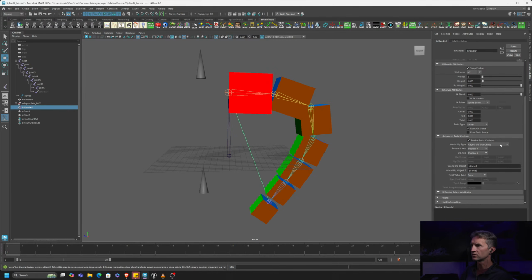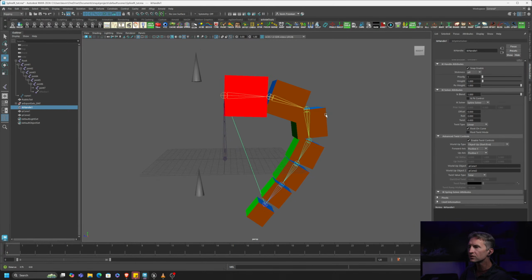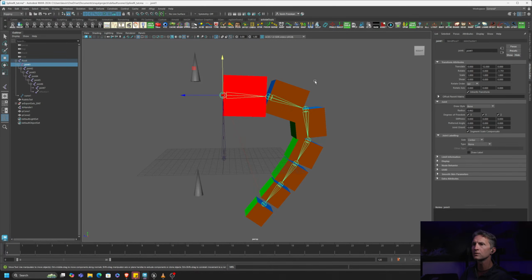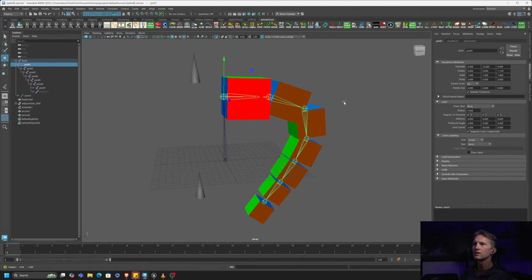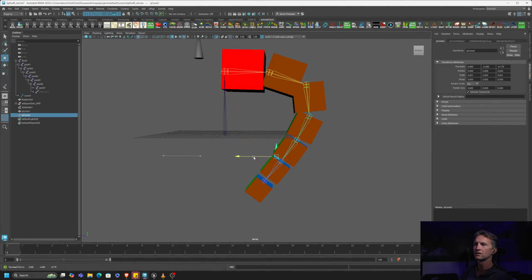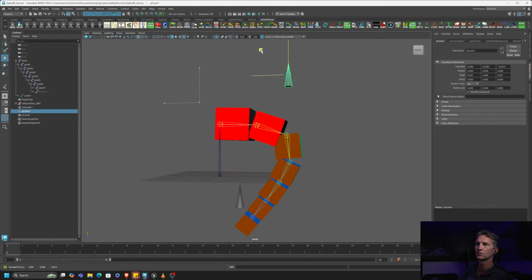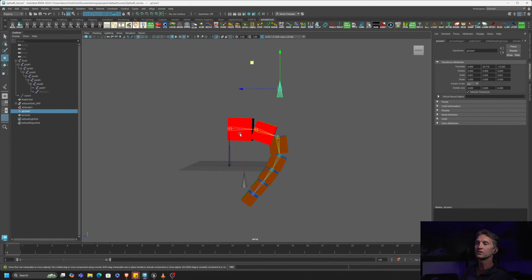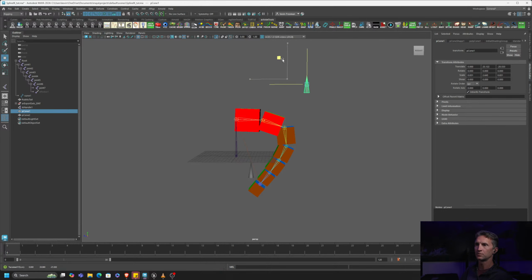Okay, now we have our twist, start up, forward axis is up, axis is Y. Is that what we want? Yes, up axis is Y. Now, depending on where this cone is, this changes which way is up, and it's based on the twist. Right now, where this cone is determines what is up, and it's graded as falloff for the entire chain. So with this cone being up here, these first 2 boxes, you can see it's able to determine up by where this cone is. The further we go along, the easier it is for it to determine.